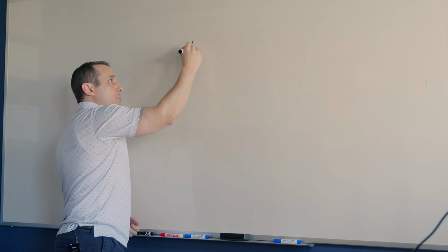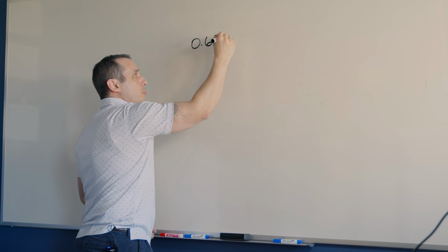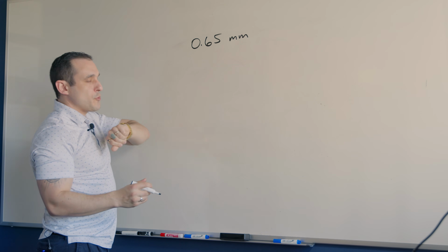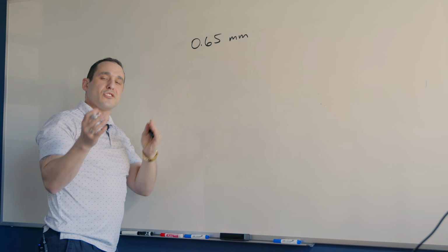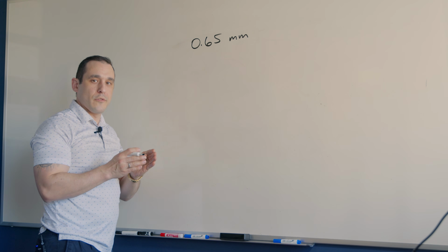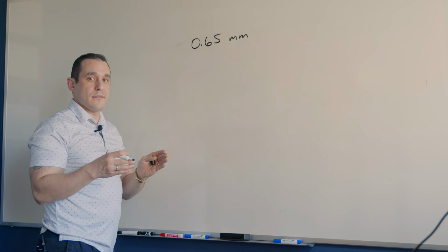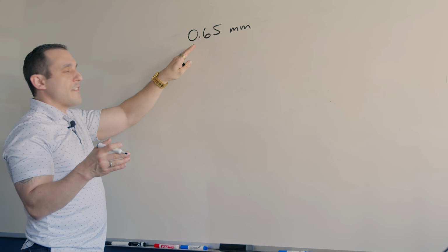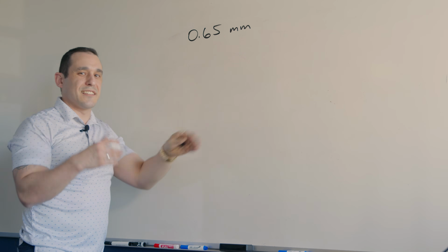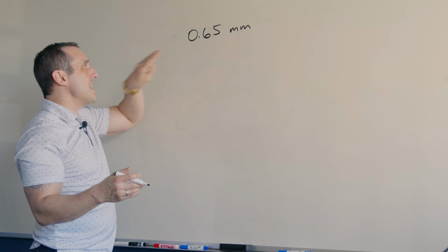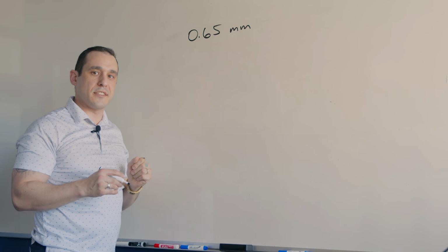So now to see a case where we might need solder mask defined pads, we would need to look at a case where we have via in pad in the BGA footprint. And so that's where we're going to look at a finer pitch BGA, such as a 0.65 millimeter pitch BGA. Now this is kind of a mid-range pitch size where it's not so tight that you have to do micro vias, but it's not large enough to do dog bone vias. Now you probably could do dog bone via fan out using micro vias, but that's a little bit going overboard. You could still do mechanically drilled vias in this footprint using solder mask defined pads.